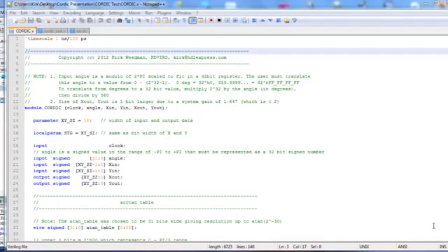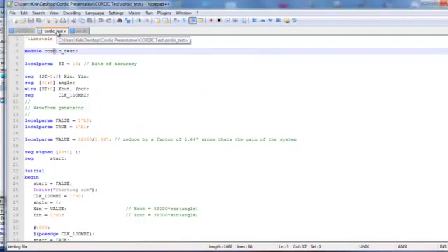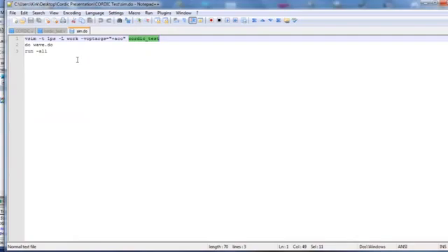This simulation consists of three basic files: the coordinate.v, which we've been looking at in the rest of the presentation, a coordinate_test.v, which is the stimulus file for this simulation, and a sim.do simulation script to run this simulation. All of these files will be included with this video on my website at www.hdlexpress.com.